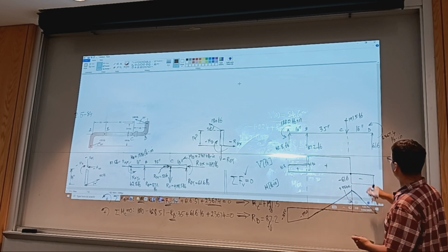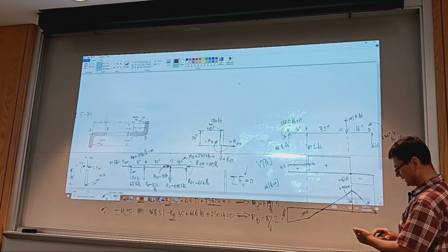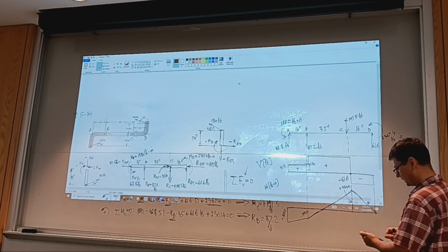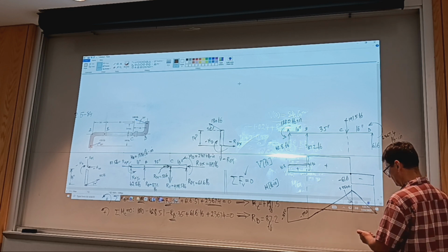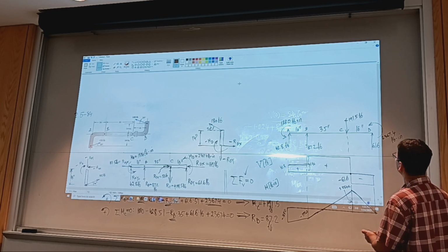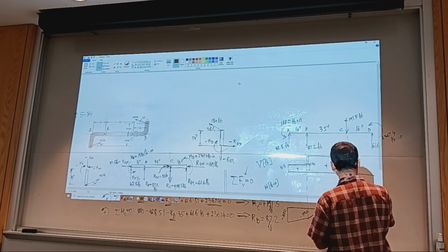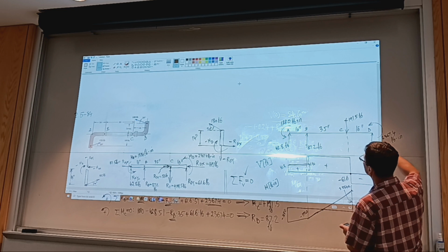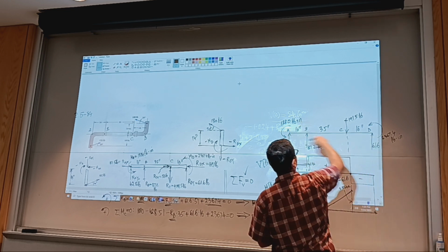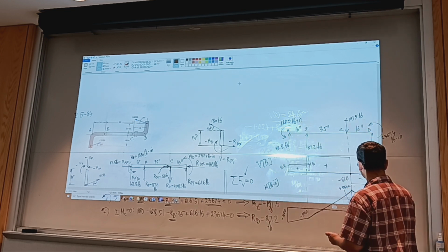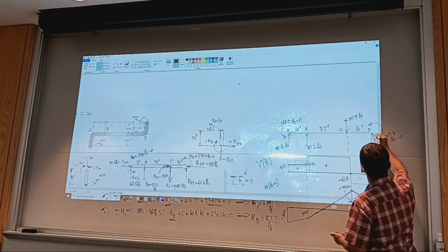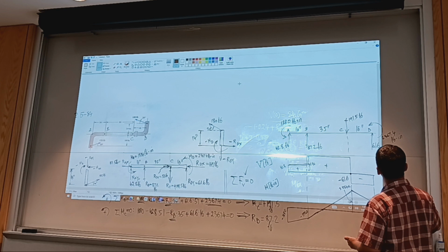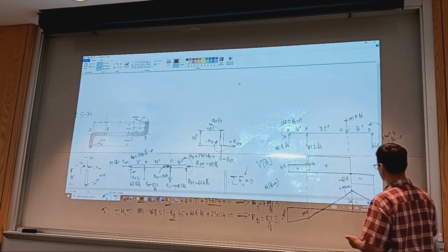And subtract 61.6, negative 61.6 times 16. I'm sorry, it doesn't go to 0. We have this moment, which is likewise counterclockwise. So the diagram will drop to 0 immediately after point D. It should end with 2367.4.